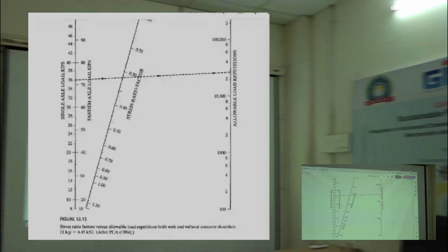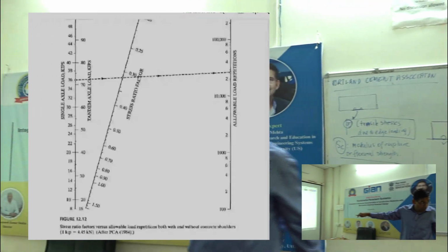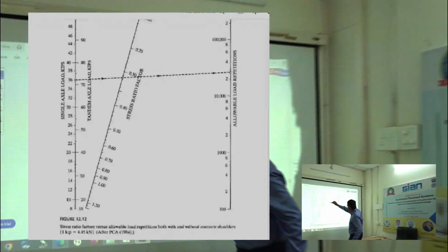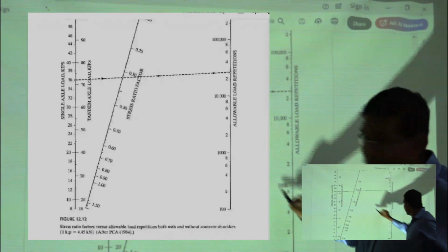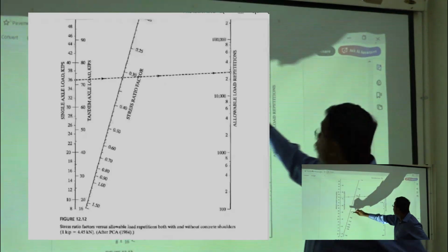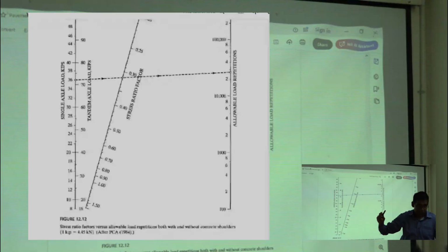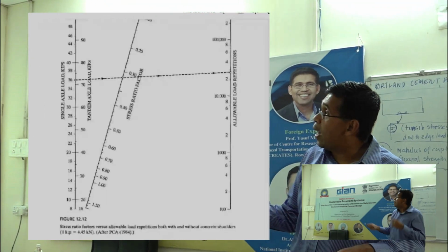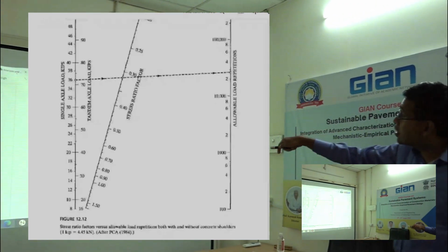So you have to do every row, you will have to find the right load. Stress ratio factor remains the same. So you are basically pivoting almost like this. As the load goes up, number of allowable repetitions go down. On the other way, if you go like this, it will go up. If you go outside the chart, if it goes too high, just call it infinite. Does that make sense? Unlimited. So that's what you have for the allowable repetition for each of these conditions.